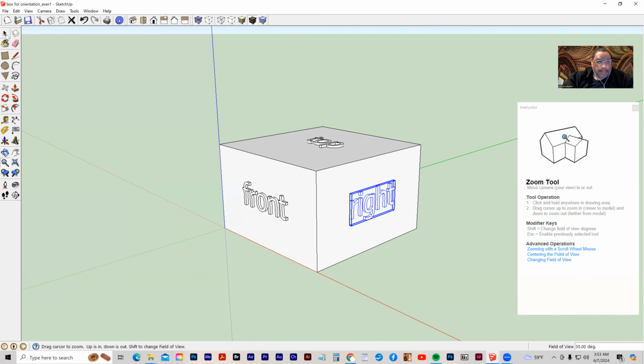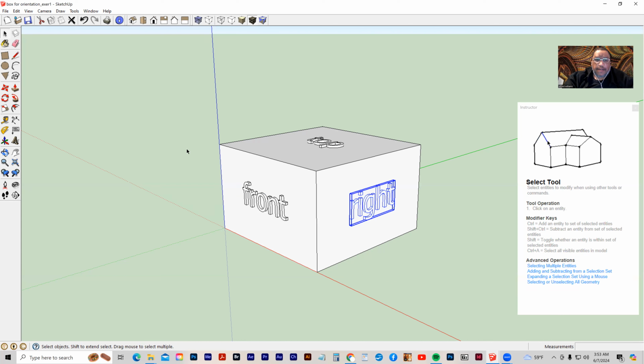So I'm going to grab my selection tool, and the first way to select is to trap select. When I trap over everything like this, everything inside of here is now a unit. And if I manipulate it, it's going to manipulate all these things together. If I move them, they're all going to be moved together. If I apply an effect, a squash or whatever, it's going to apply that to all the shapes. I'm going to click away. That's how you deselect.